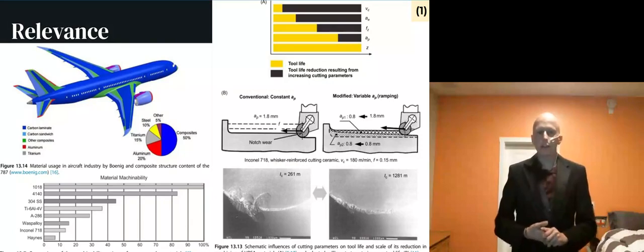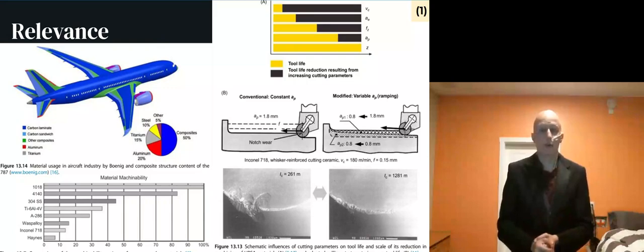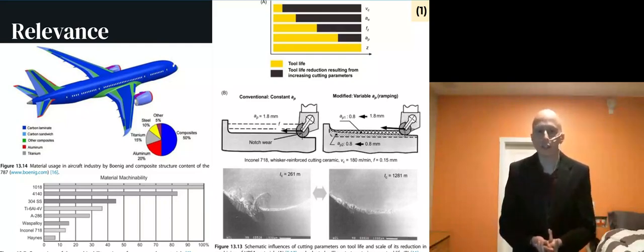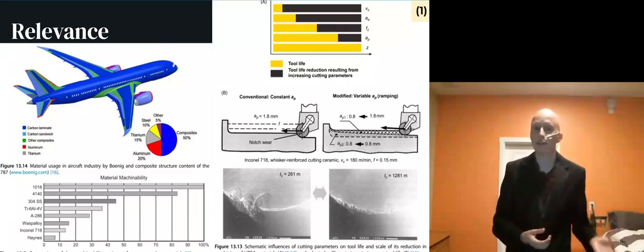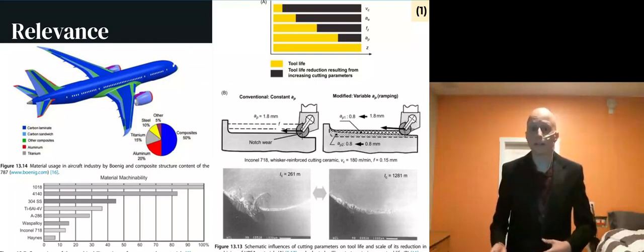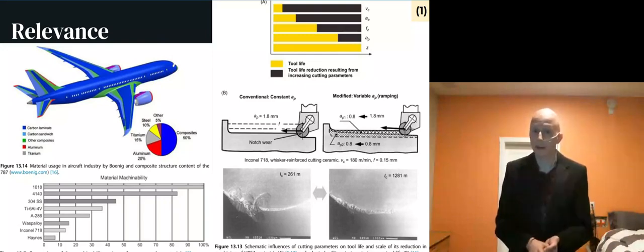The importance of determining the machinability of engineering materials lies in making job processes more economical and optimized. This can be the goal of decreasing machine runtime, energy consumption, temperature output, or increasing tool life and surface finish. Large engineering companies can look at the material properties they need for a certain application, such as the wingtip of an airplane for aerospace, and weigh that against that material's actual machinability and determine whether the use of this material in this application is viable.